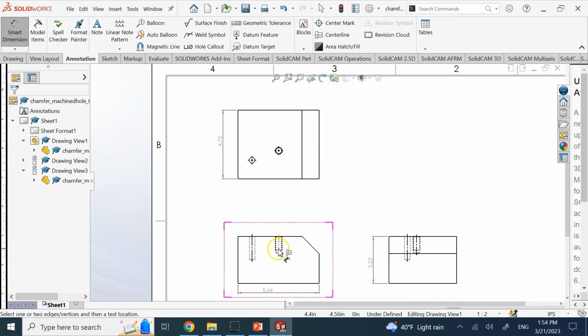Using the two other views, you can easily imagine the 3D shape of the object and all of the details. And the third view can easily be eliminated. Just like in this case, this third view is literally redundant. So if I want to distribute the dimensions, I'm not going to put anything on this right view because I can easily just get rid of this part.